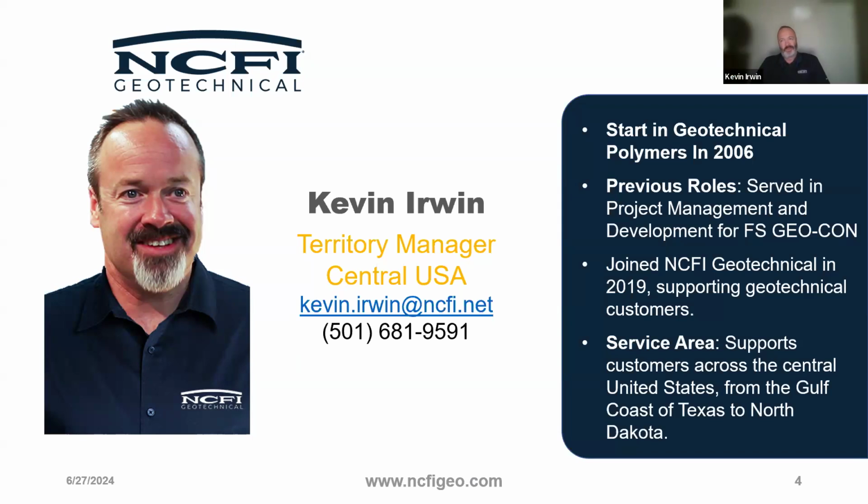Formula for soil stabilization, depending on the soil type, it really depends on how much flow you think you need. But of any of the systems, what I typically see out there is the 24003. It's a good medium speed foam. It's a 4 pound minimum density, so you've got 80 psi out of the box, and it's only going to go up from there. So you've got a good range of depths you can get to, because it's a little bit slower than some of our other systems that are designed for lighter weight lifting.